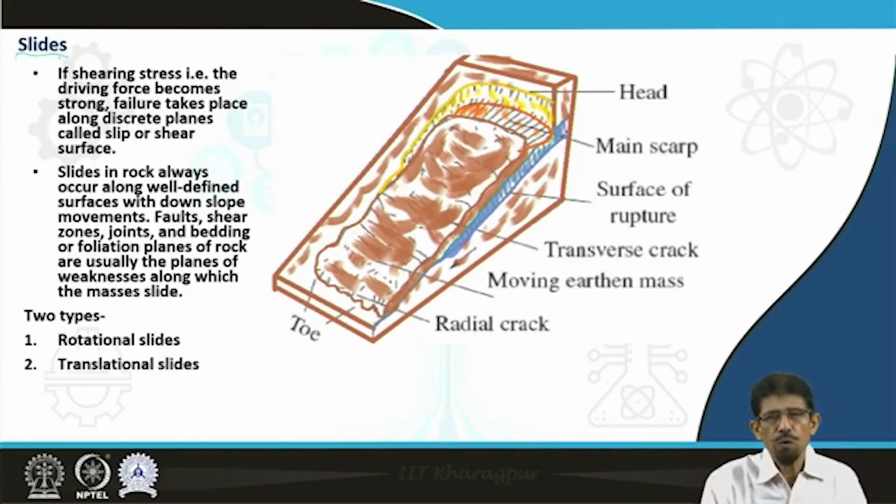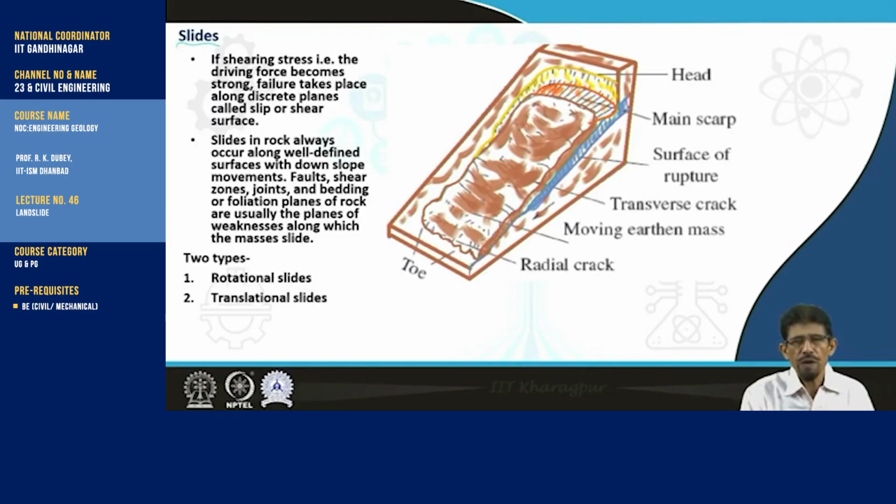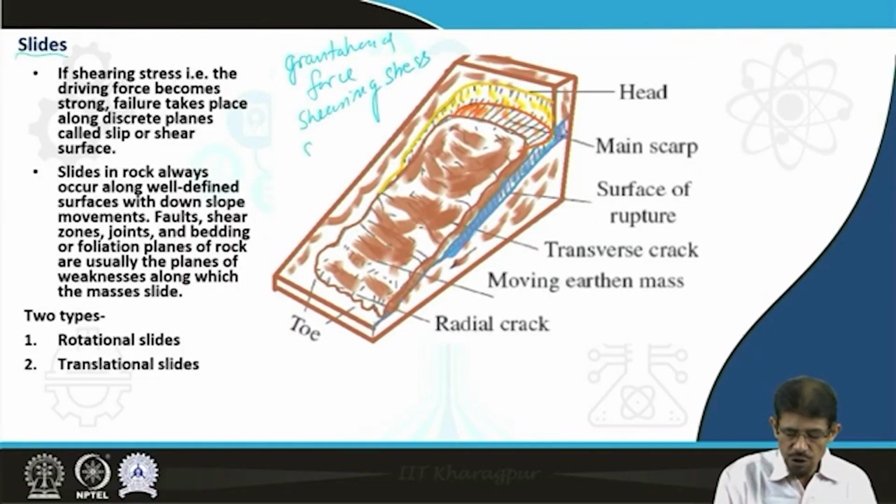And overall, if the land is going to slide, we recognize it as a landslide if regolith is present. But this term landslide, which was referred to for the landmass, now we are going to utilize as a synonym for all types of slides. The landslide, you can see, is a play between this gravitational force and the shearing stress and shear response of strata.